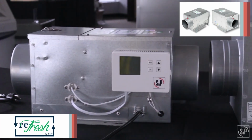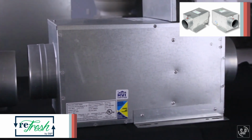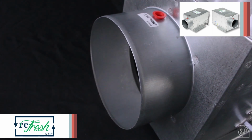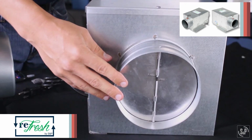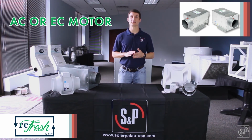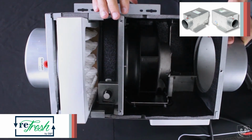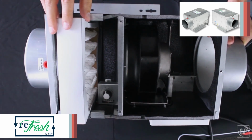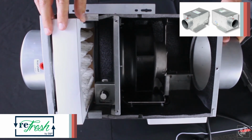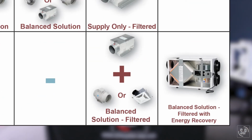The Refresh series is S&P's ultimate all-in-one supply fan for outside air. This rugged inline fan was specifically engineered to supply fresh air to the residents with its galvanized housing, filter slot, acoustic insulation, and preset fan speeds. There are multiple Refresh fan variations including low profile, AC or EC motors, and factory installed power cords and ES24V controls. We also offer 2-inch thick MERV 8 and MERV 13 filter options to make sure the outside supply air is clean and help improve IAQ. The Refresh series can be used as a supply-only or combo system to provide fresh air.